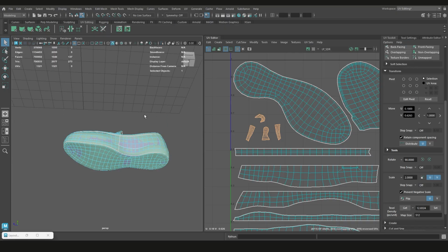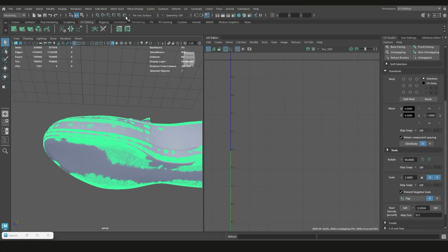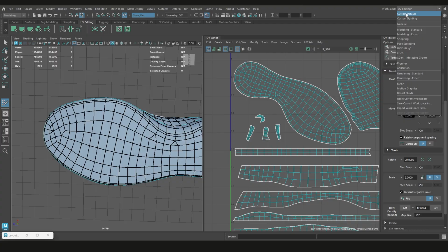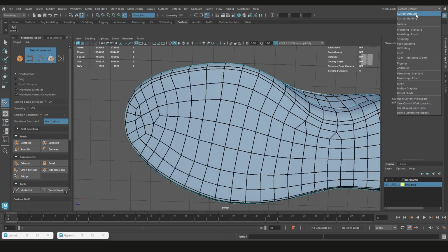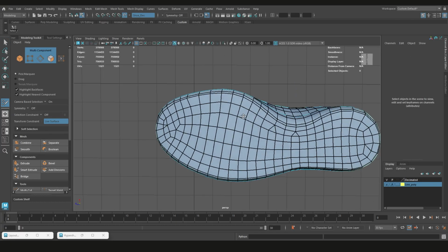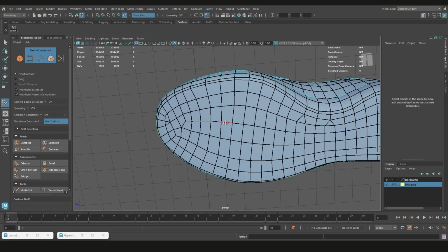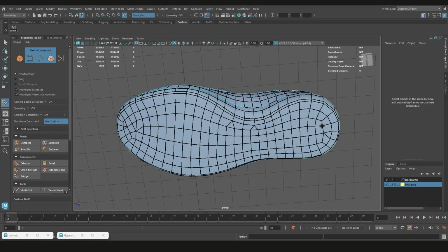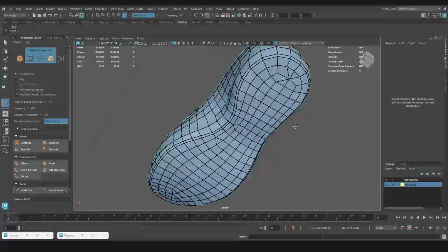I'm going to press Ctrl+1 to get out of solo mode. I'm going to go into object mode, go back here and make that a live object, click on this one and press Ctrl+Shift+Q. We want to go back to custom default. By the way, yours is probably just called default, I don't know what it'll be called by default. Okay, so I just want to merge some of these. This one here is definitely one that can be merged, so I am just going to do this, and that. Again, you don't want them right on the edges here, so no triangles pretty much on the edge.